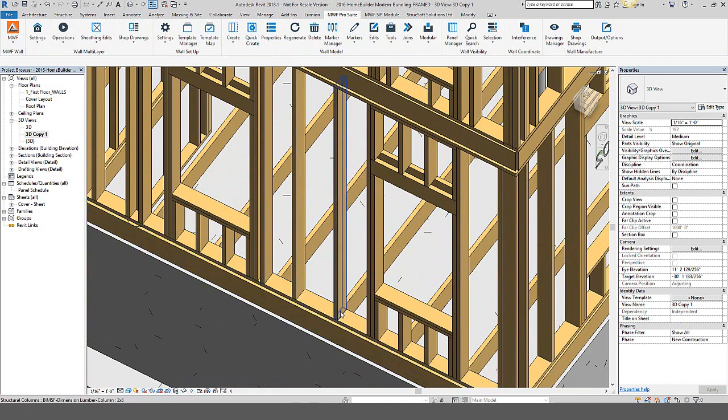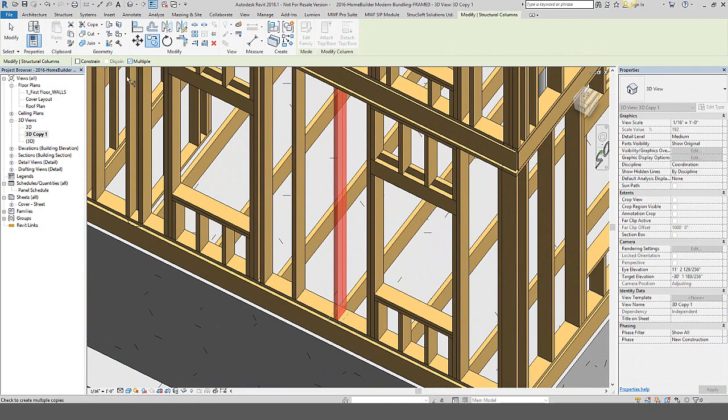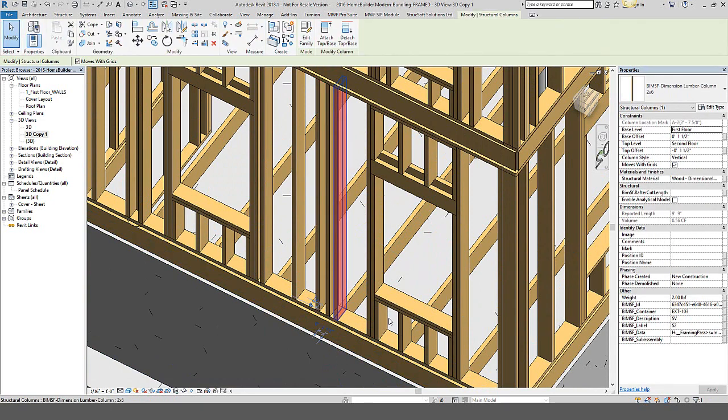So let's take a look at another operation here. Let's use Revit copy to copy this stud over here, and then again. So I've selected the original member S2. I've copied it here, and you'll notice it keeps the same BIM-SF label S2 and S2.